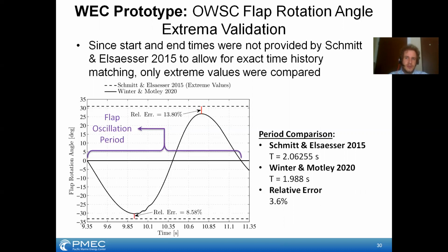And this is going to be due largely to the acceleration damping that occurs in the rigid body motion model. To keep it stable, you definitely need to specify some damping, but this is clearly too much damping. And so we're also trying to optimize the level of damping so that you not only get the period to match nicely, but you get the amplitudes to match nicely as well. Since you can see the period is only off by 3.5% roughly compared to the amplitude errors.